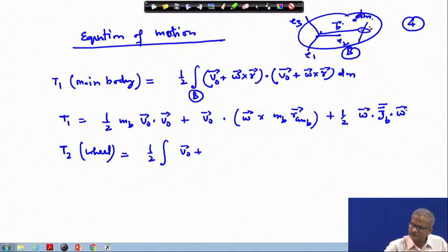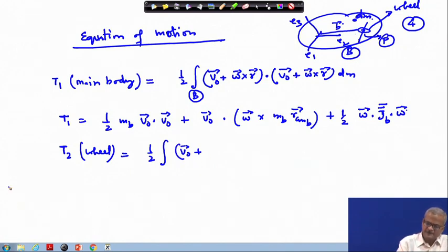Okay, so this is the point we have earlier taken as P, and this is your wheel. Either I can break it and write it as V0 plus the velocity of this point with respect to this, which will be omega cross B, plus, now any point on the wheel itself will have certain velocity with respect to the center of mass.